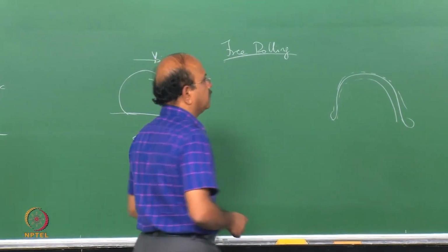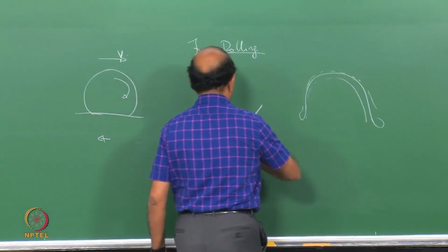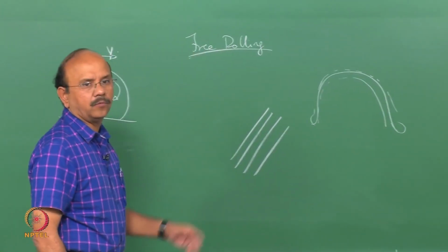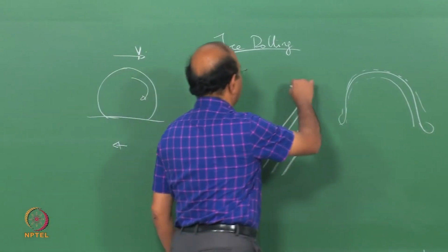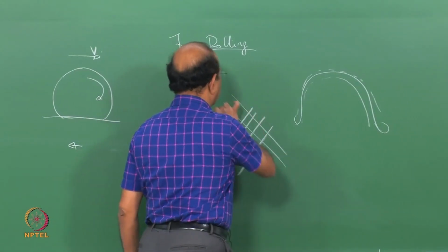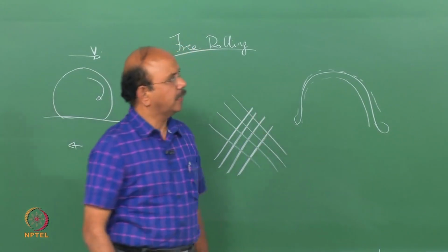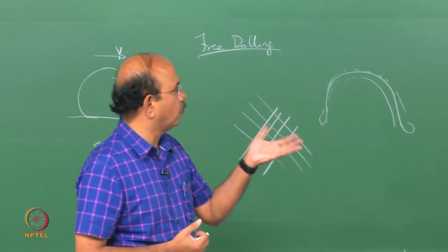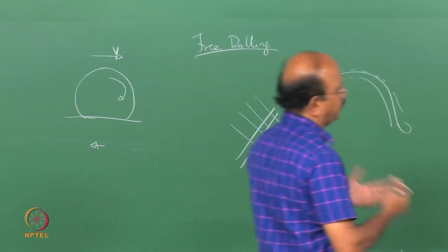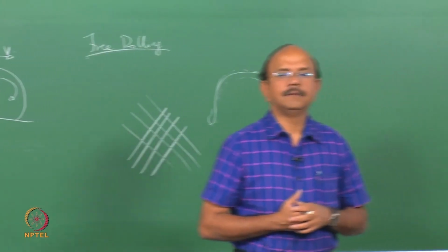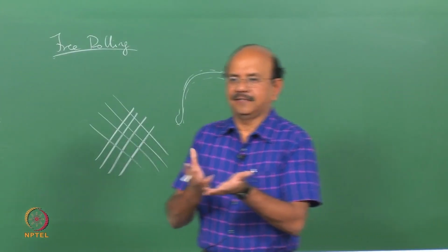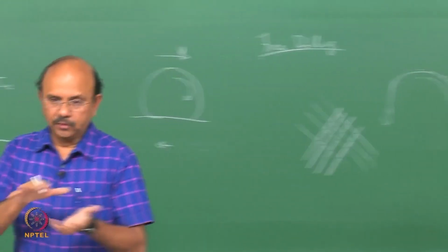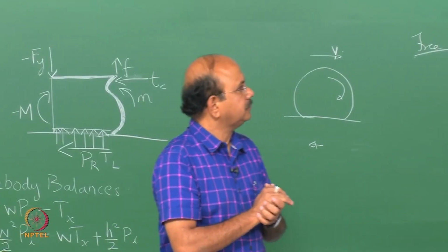For example, if you look at it from the top, you have wires running like that in one of the belts, and running like that in another belt, and so on. The two working belts, 1 and 2, are very important, and as I said, they give the lateral stiffness and the longitudinal stiffness to the tread.